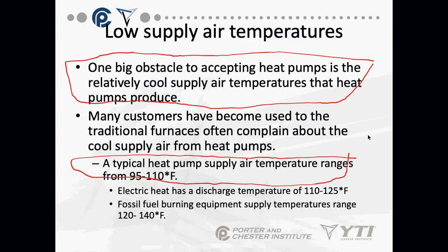However, even though you don't feel this 120 degree air blowing on you, it doesn't mean the heat doesn't exist. I may not feel that 120 degree air, but if I'm blowing 110 degree air into a space that's 65 degrees, that space is going to heat up. It might just not feel like it to the customer. Anybody have any questions on this slide? This is sort of important.